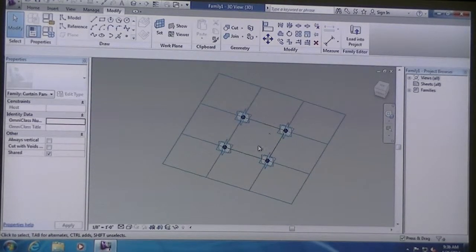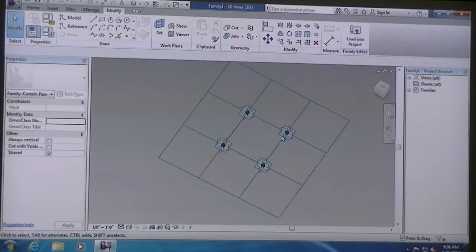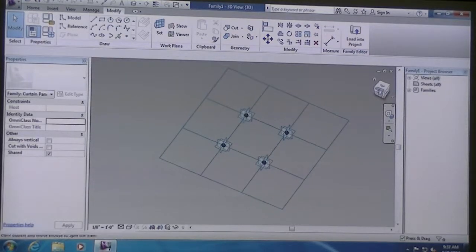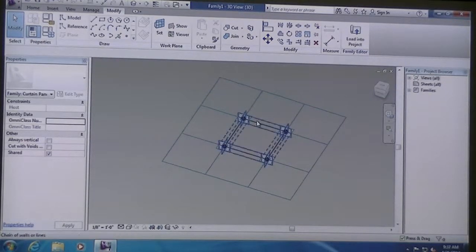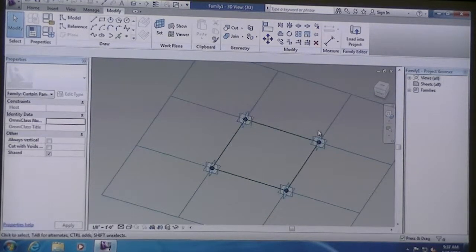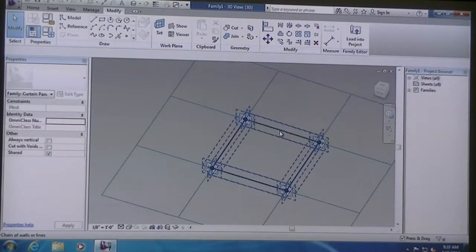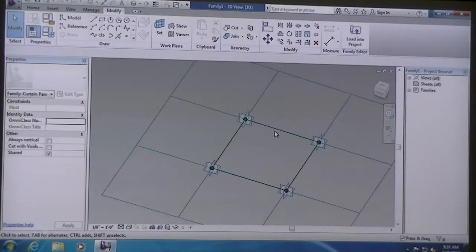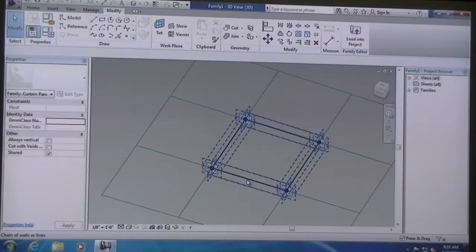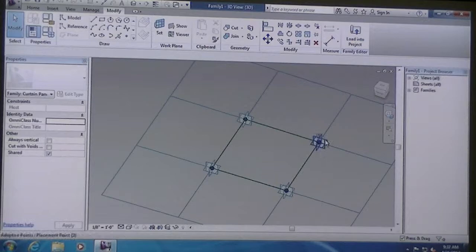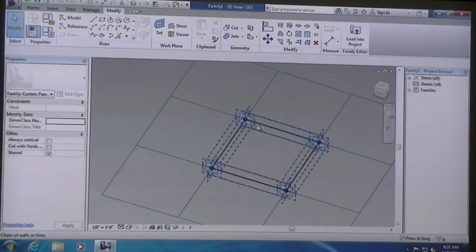When we're going to be applying this to a vertical surface, and we're concerned with what's on top and what's on bottom, when you look at the top view, if it says top and you're looking at the front, then this line that's on the back side will be the top of the guardrail. So this down here at the front is going to be the base. And these would be the verticals on either side. And again, this is the top.